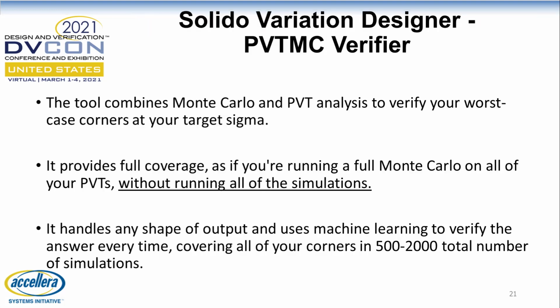So we used the PVT MC verifier for the statistical analysis for this latch. The tool combines Monte Carlo and PVT analysis to verify your worst case corners at your target sigma. It provides full coverage as if you're running a full Monte Carlo on all your PVTs without running all the simulations. It handles any shape of output, Gaussian or non-Gaussian distribution, and uses machine learning to verify the answer every time.